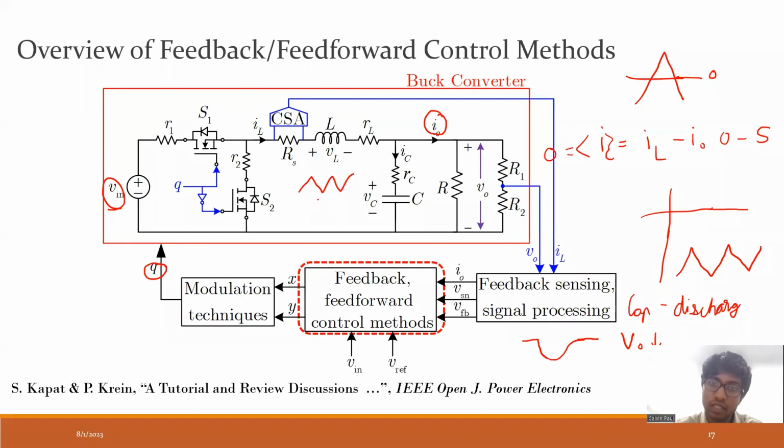Then see, the current in the inductor is like this, and it has a frequency. Because of this flowing, and because of the various passives and parasitics, electromagnetic interference signals are generated. We do not want this application to generate EMI which exceeds a certain value.